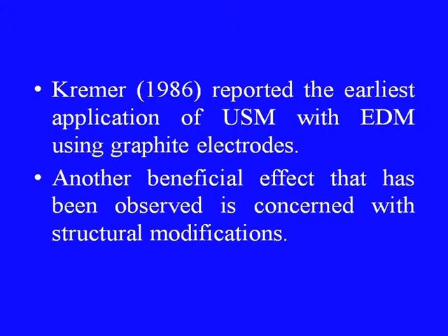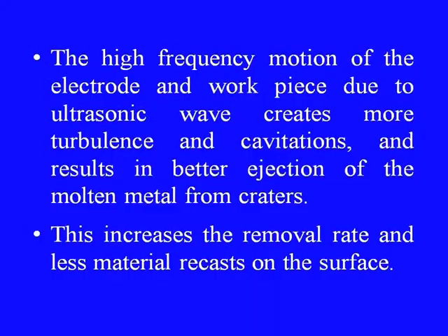Another beneficial effect that has been observed is concerned with the structural modifications because of this hybridization. The high frequency motion of the electrode and the workpiece due to ultrasonic waves creates more turbulence and cavitations, and this results in better ejection of the molten metal from the craters.